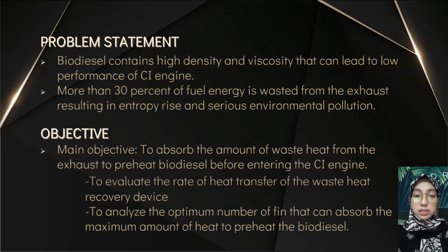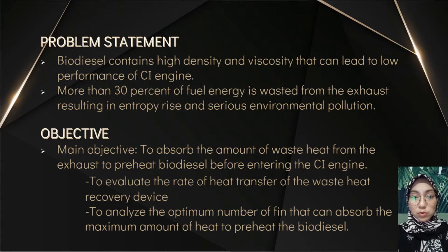The main objective is to absorb the amount of waste heat from the exhaust to preheat biodiesel before entering the CI engine, to increase CI engine performance and decrease exhaust emission. The detailed objective is to evaluate the rate of heat transfer of the waste heat recovery device to analyze the optimum number of fins that can absorb the maximum amount of heat to preheat the biodiesel.